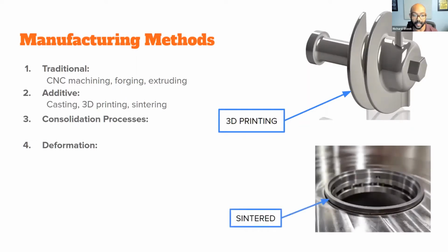Another option is sintering. Sintering is kind of a unique bonding consolidation process, but it's also kind of casting in a way too. It's basically taking a mold, pouring in powdered metal, and then compressing it to high pressures and then temperatures as well. Well, sometimes high pressures, but essentially with the high temperature, it fuses everything inside together. There's usually some bonding agents involved in that as well. But usually that's meant for like seal faces. You can typically find like jewelry as well in those same applications.